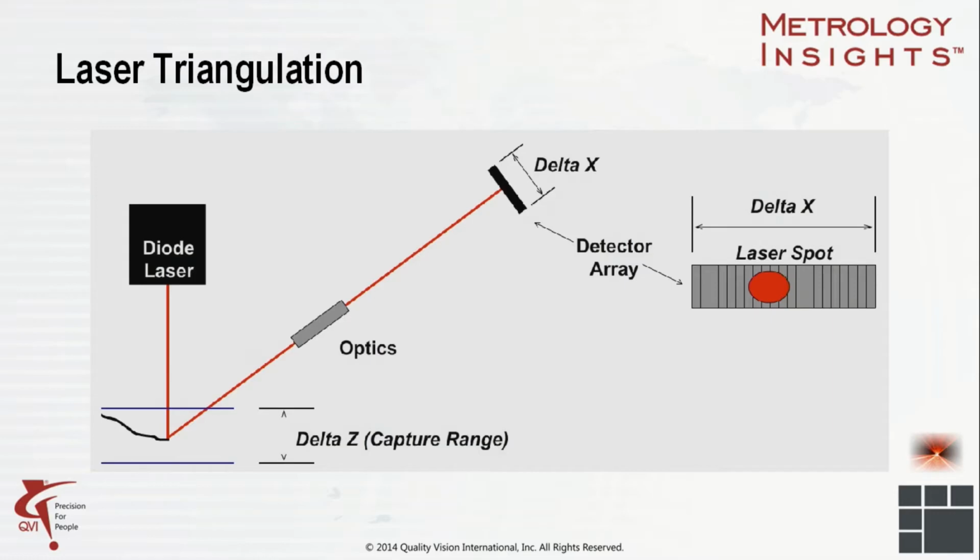When surfaces are both textured and very shiny, the laser light is scattered when it reflects off the surface, so that less of the light returns to the detector. This weak signal can contribute to data losses and reduced accuracy. Measuring inside a hole or cavity can also be limited. If the opening is too narrow, the laser's return path may be blocked.